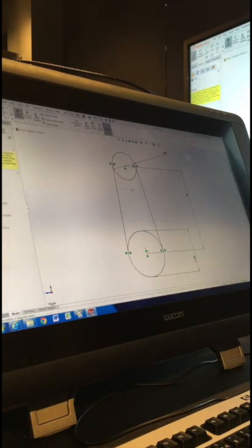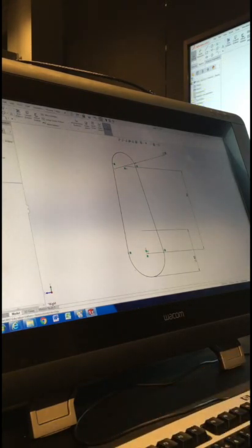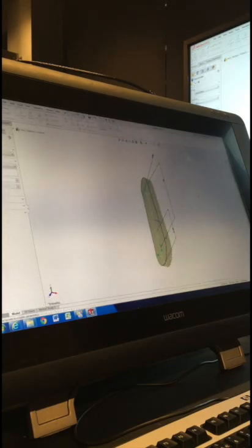All I want to do is trim over that little section of circle and that bottom section of circle. That creates now our outside shape. Then I can hit Escape to cancel the trim tool, and then I'll go Features, Extrude. And this time when I do it, because there's only one shape there, I'll automatically get a preview of the extruded shape.